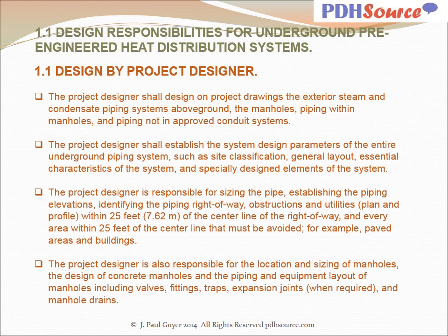The project designer is also responsible for the location and sizing of manholes, the design of concrete manholes, and the piping and equipment layout of manholes, including valves, fittings, traps, expansion joints when required, and manhole drains.